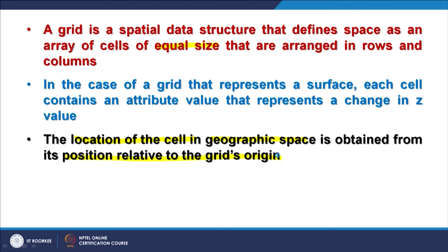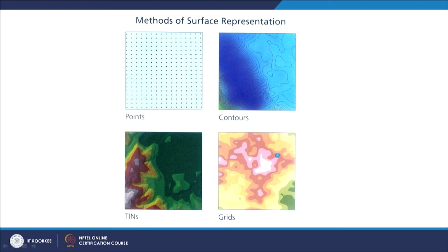If it is still in geometric domain, you would get geometric coordinate. So generally, if you download a digital elevation model, whichever of the free digital elevation models which are available from different portals based on different techniques, all of them are nowadays georeferenced. So for each point location or each cell location, you not only get the Z value, but you also get X and Y in terms of latitude, longitude.